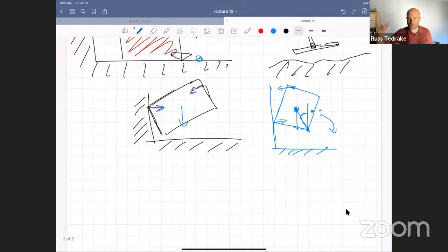Okay. My controller is going to push to the right with force 4 for the first 1 second. After that, I'm going to enter this next controller mode, which is start balancing the forces. So I'm going to write a quadratic program where I'm going to define my decision variables as the force. Let me call this point A with the coordinate frame like this. And this is my contact point C with the coordinate frame like this.